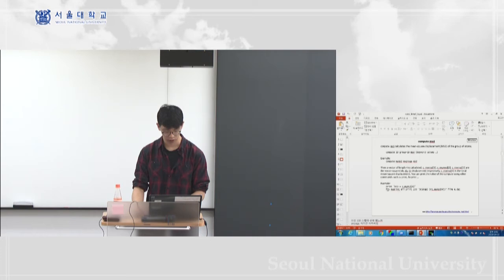So if you do this, like fix myPrint and let it print out the 4th value of the myMSD, and this 100 here, then we are gonna print out this mean square displacement every 100 steps to the file named e.dat.